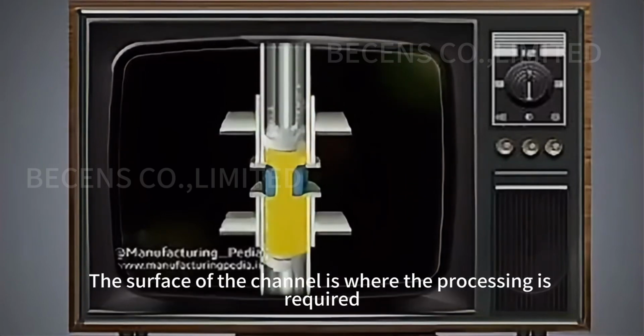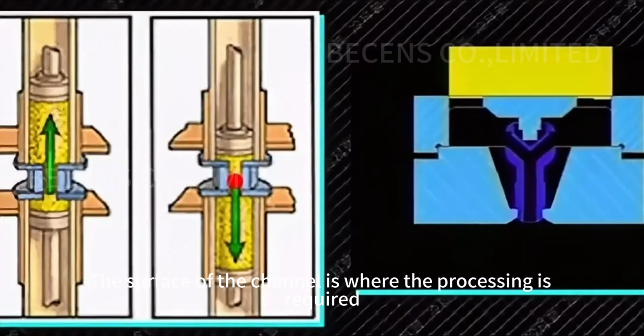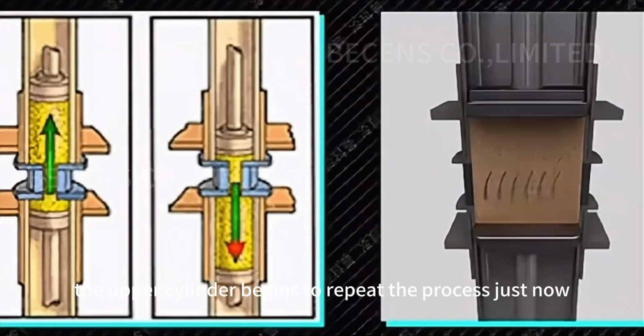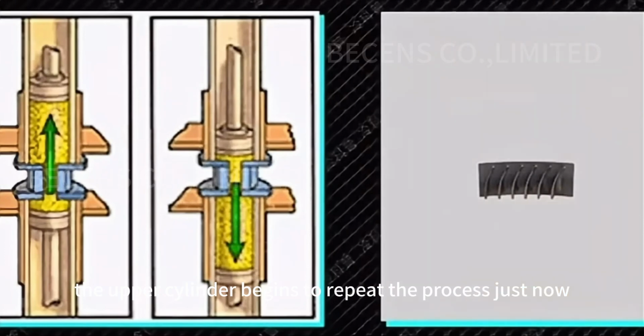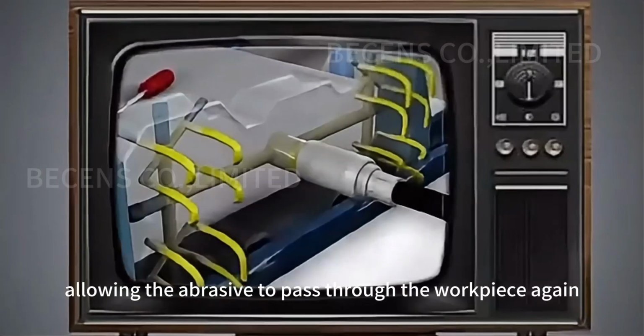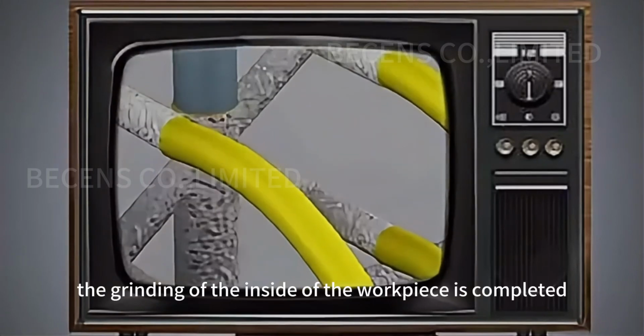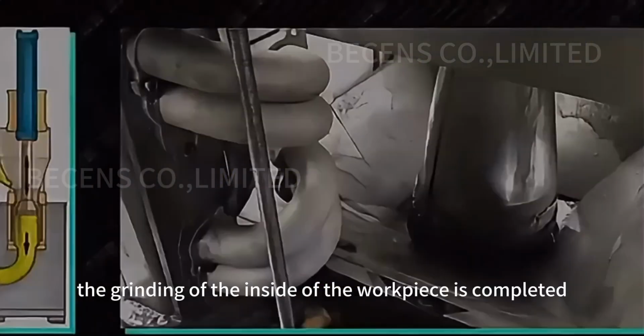The surface of the channel is where the processing is required. After the lower piston reaches the top, the upper cylinder begins to repeat the process just now, allowing the abrasive to pass through the workpiece again. After several cycles, the grinding of the inside of the workpiece is completed.